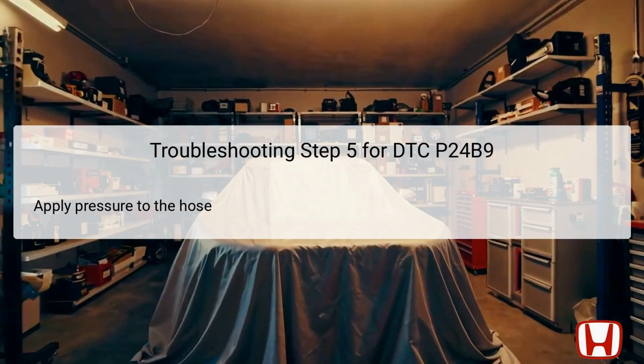At this stage of troubleshooting, the technician applies pressure to the hose connected to the canister one-way valve. This application of pressure helps to validate whether the one-way valve is functioning correctly, allowing the technician to gauge the integrity of the EVAP system. Ideally, under normal conditions, the pressure should hold steady, reflecting the operational reliability of the entire system.